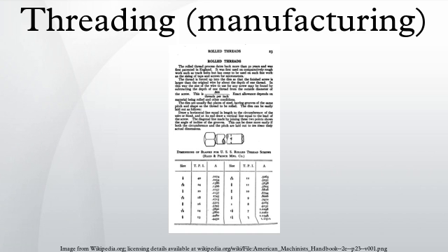Form milling uses either a single or multiple form cutter. In one variant of form milling, the single form cutter is tilted to the helix angle of the thread and then fed radially into the blank. The blank is then slowly rotated as the cutter is precisely moved along the axis of the blank, which cuts the thread into the blank. This can be done in one pass, if the cutter is fed to the full thread depth, or in two passes, with the first not being to the full thread depth.